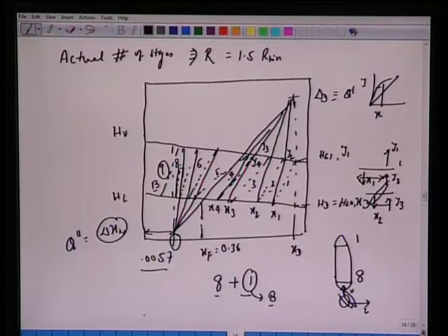Alright, so in this lecture we have taken this example based on the Ponchon-Savarit method, where we have addressed how to calculate the minimum reflux, how to calculate the total number of plates corresponding to 1.5 times R min, or the minimum number of plates corresponding to infinite reflux ratio. So essentially start with the hxy diagram and mark all your enthalpy points, xy coordinates, and then do this staging, trying to identify that at every stage the vapor and liquid leaving are in equilibrium.